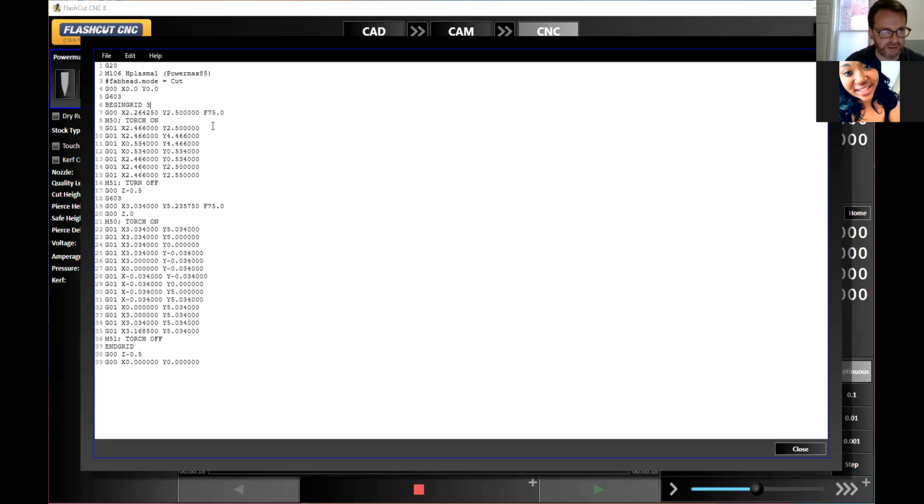Yep, 3 columns, 3 rows, 0.5. And that's where all these drawings are going to start, at X 0.5, Y 0.5. There's 3.5 inches spacing in the X direction, 5.5 in the Y. Doing it column by column, and we'll cut column by column.